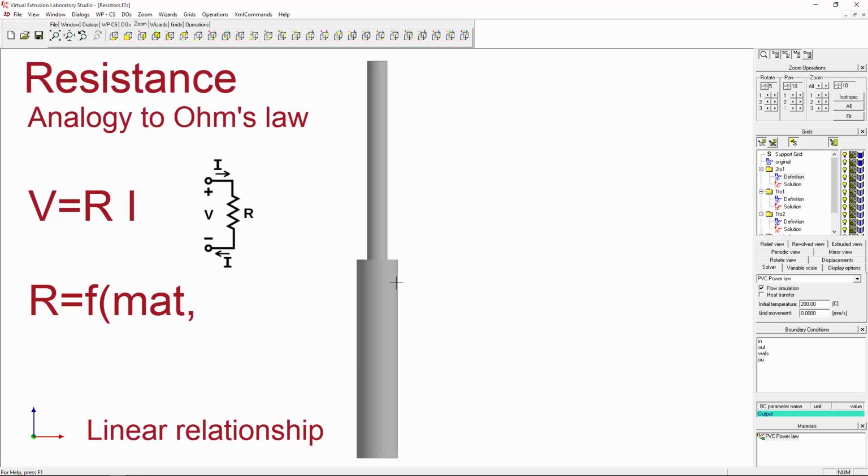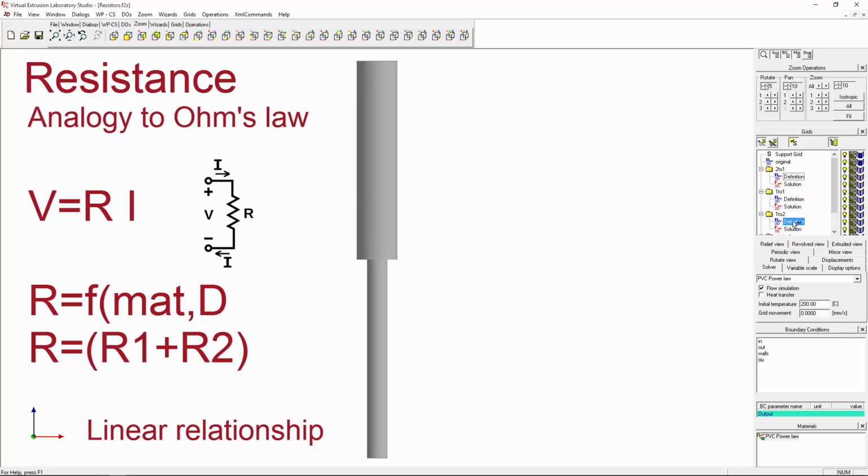So if we make, let's say, the lower part of the channel thicker, we lower the resistance for the whole system, because the resistance of the whole system is the sum of the resistance of this narrow part and the resistance of this thicker part. That of course influences the voltage and current going through. Similarly, we can do something different. We can just have the thickness here. So these two will probably give us the same resistance.